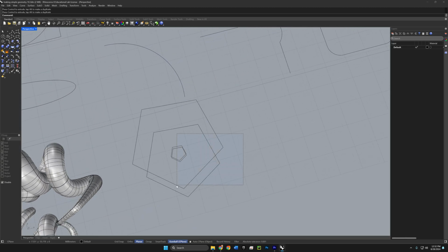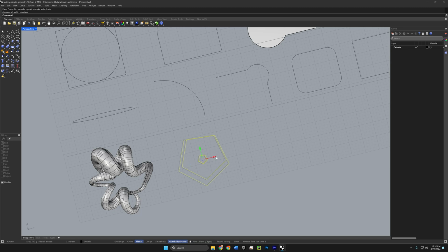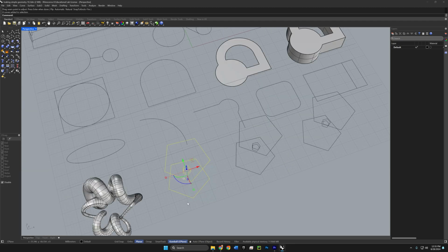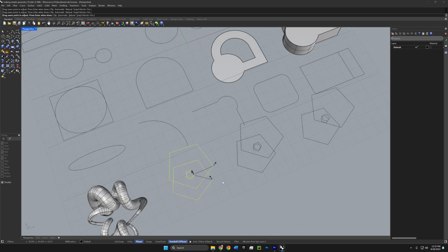Let's make a couple of copies of this set of curves. So we'll just tap Alt again as we drag over and do that one more time. Now we'll select all of these curves and run the loft command. And it's asking in the command line if we want to drag the seam point to adjust. Because the seam point is well aligned among all of the curves, and because the arrows are all going in the same direction, it looks good. If we would need to change anything about it, we can click on these arrows actually, or we can even move these points around in space. But again, I'm going to put this back and switch the arrow back to the previous direction and push enter.